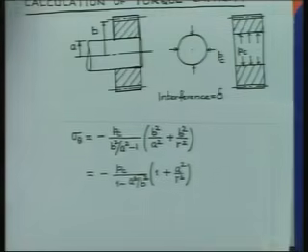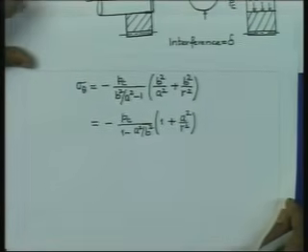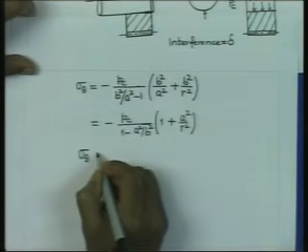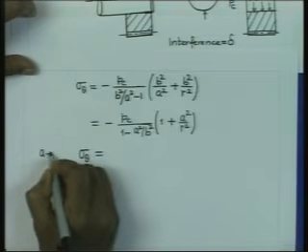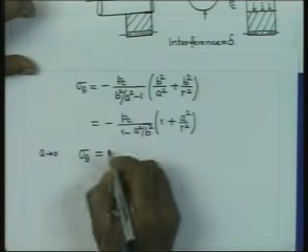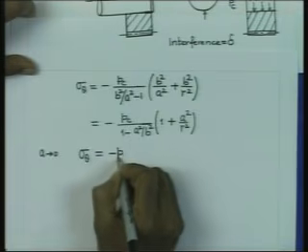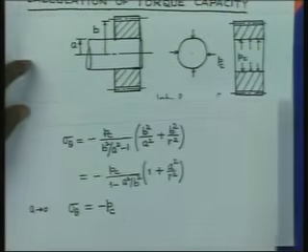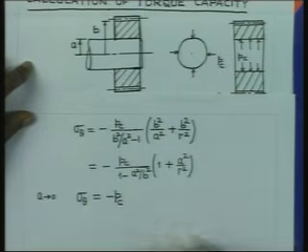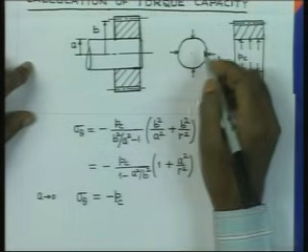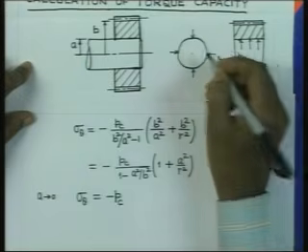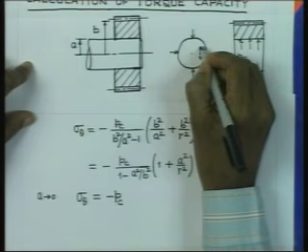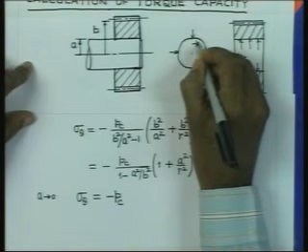So, that is the variation of the sigma theta stress, and if you consider now A tending to 0, then you find that it comes out to be equal to minus Pc. So, the stress in a thick cylinder with internal radius 0 is going to be minus Pc in the circumferential direction. So, therefore, at a point here we are going to get the hoop stress is equal to minus Pc.